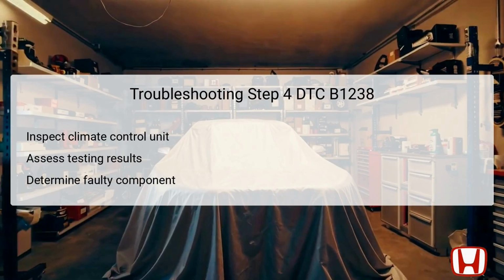If issues are identified with the climate control unit, especially if it shows abnormal responses during diagnostics, it could very well be the source of the DTC B1238. This deliberation will help isolate the component that requires replacement or repair, bringing clarity to the overall diagnostic process.